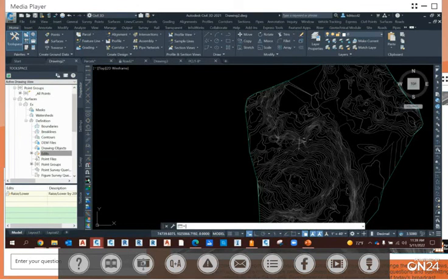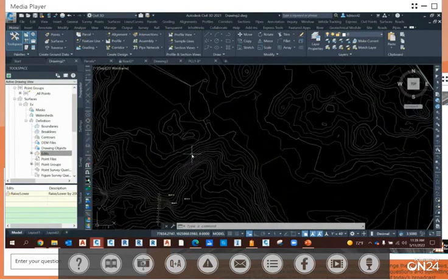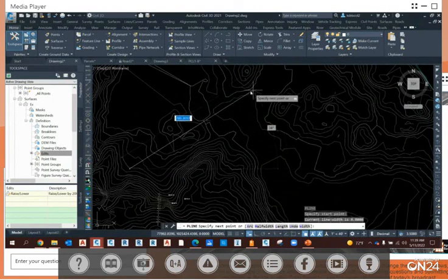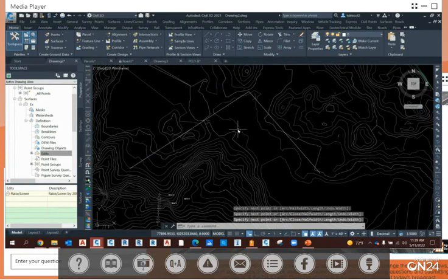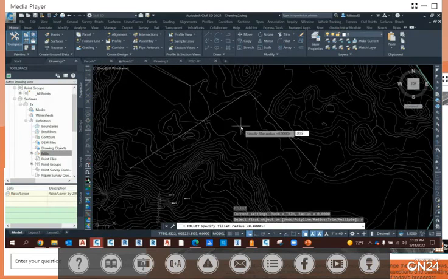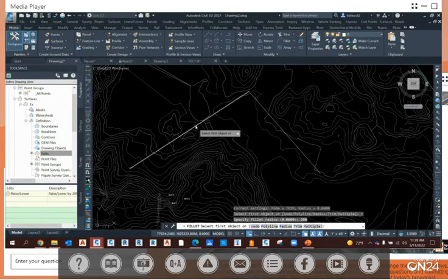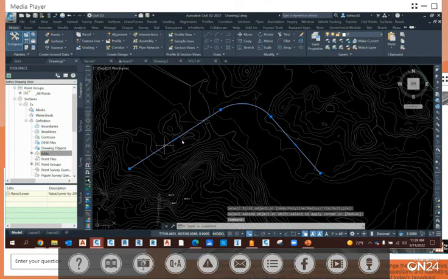So we also talked about this idea of working with parcels. And working with parcels and alignments and things like that. Well, let's look at alignments. In AutoCAD, if we draw a tangent in, a tangent out, we can come in and say, we want to run a fillet, and we can say that fillet radius, I'm going to say 200 feet. I'll pick my tangent in, I'll pick my tangent out, and there's my 200 feet. And then I have to go in and add stations based upon perpendicular to my line work.